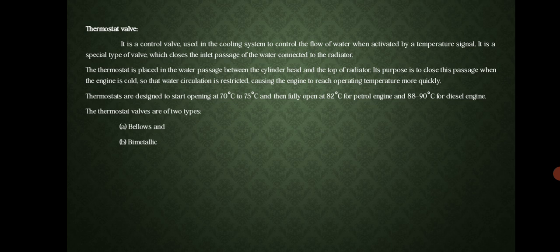Thermostats are designed to start operating at 70 degrees Celsius to 75 degrees Celsius and then fully open at 82 degrees Celsius for petrol engines and 88 to 90 degrees Celsius for diesel engines. The thermostat valves are of two types, bellows and bimetallic.